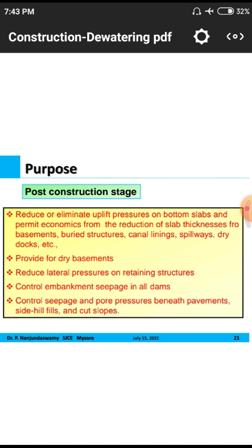Likewise, it depends upon the length of the slab. The Ly by Lx ratio, the length in the x direction and the length in the y direction, is related to one-way slab or two-way slab. If the Ly by Lx ratio is less than 2, it leads to a two-way slab. Greater than 2 means automatically it leads to a one-way slab. So we have to go for different designs to reduce these cracks.